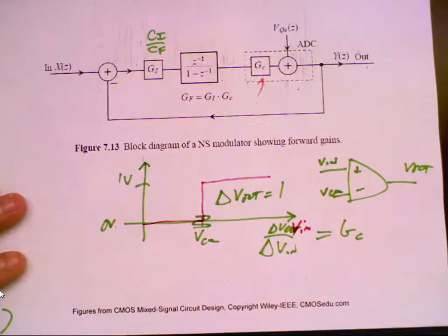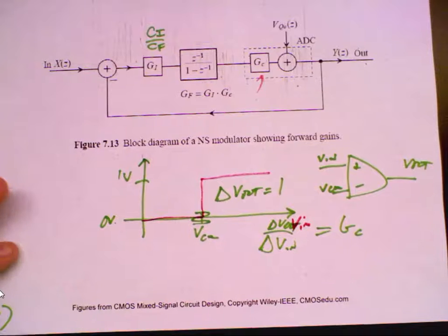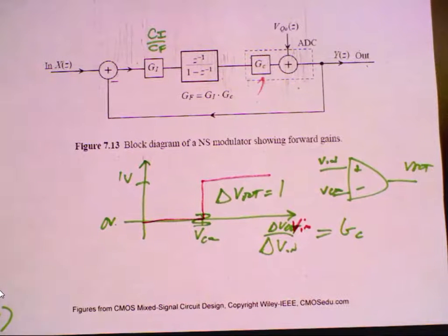Today in the presentation, there was a comment in the dissertation that said the quantizer gain goes to 0. Immediately that set off a red flag in my mind, because what's the only way the quantizer gain can go to 0? Yeah, V out is stuck, which means the input to the modulator goes to a large value, so the output can never average; it gets stuck.